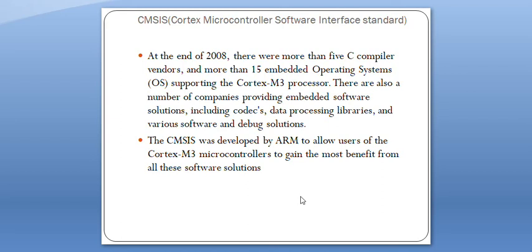If you want to do an LCD interface, then basically you just include a header file, and when you include a header file, indirectly that program is going to call the lcd.h and lcd.cpp files. In the lcd.cpp file, you'll be writing all the definitions, like whether you are going to send the command or the data. So the LCD program itself is huge, which has 100 lines of code. But in the Arduino environment, with the help of one single library, you can perform many operations like clearing an LCD, clearing the first line in the LCD, everything could be done.